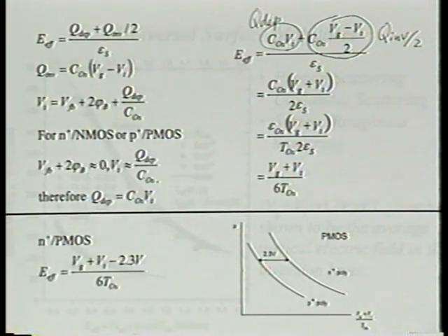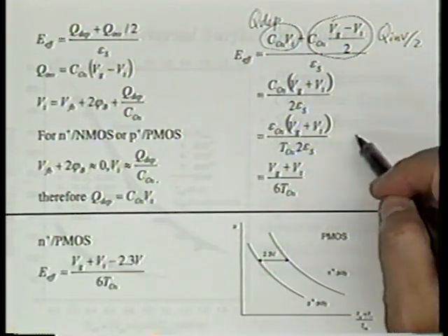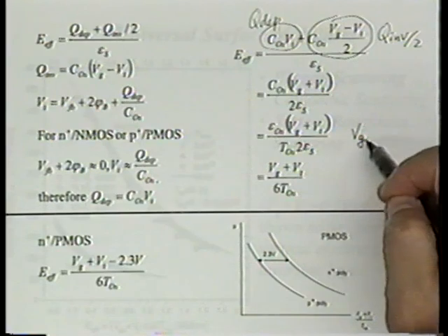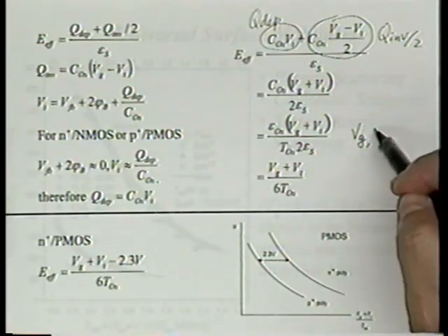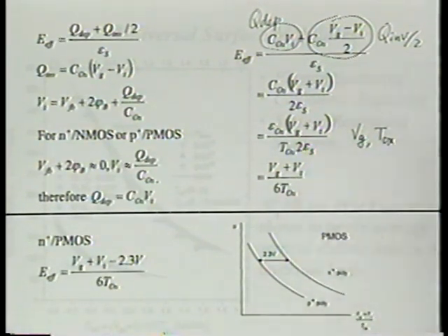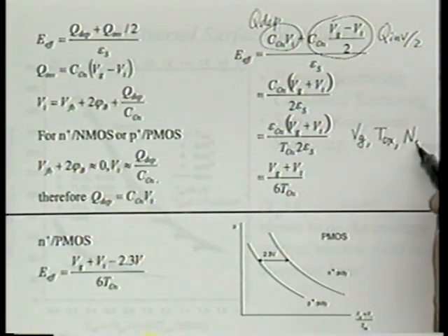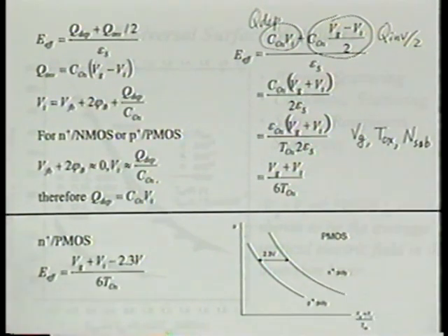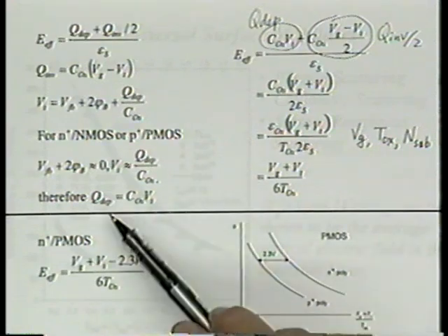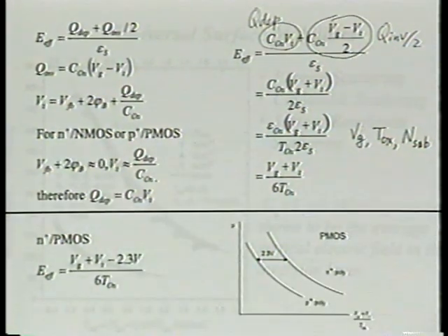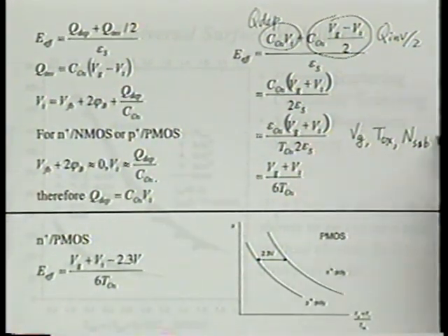We said the mobility is a function of VG. Certainly it's a function of VG, you see here. We said mobility is a function of Tox. You see it here, no problem. We also said mobility is a function of N sub. Do you see where that might come in? It's VT, exactly, because it's the Q depletion term. We said also a function of V sub.